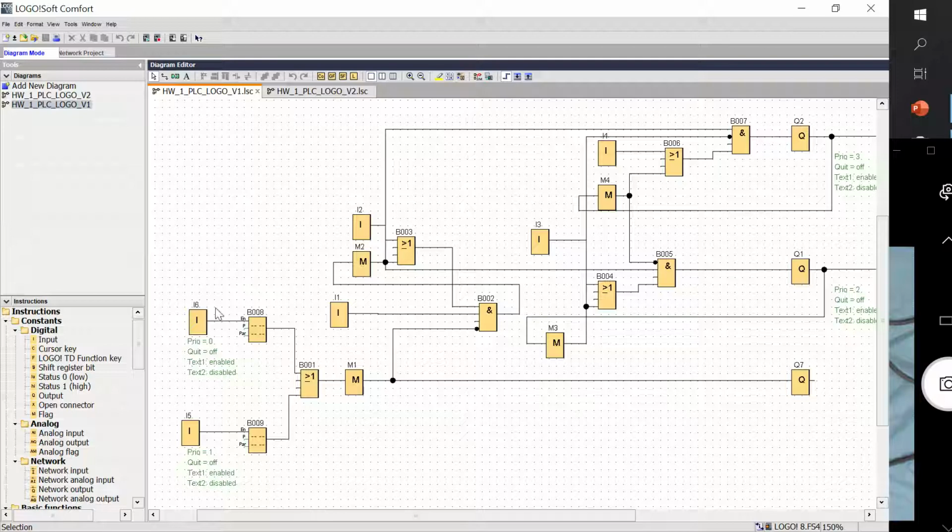As a change, I will start by explaining the PLC program according to the version 1 solution of homework 1 using the function block. Those are the blocks responsible for reading the input status of the PLC, and those are special blocks where we can display a message on the PLC screen. That may be useful for diagnosing the PLC status, or for interacting with the operator, telling the operator there are faults, the running status of the individual components, and so on.